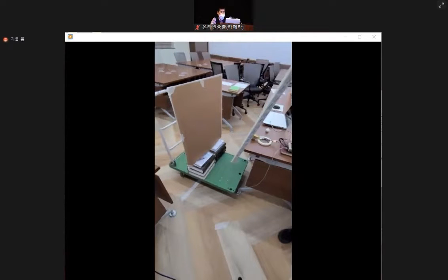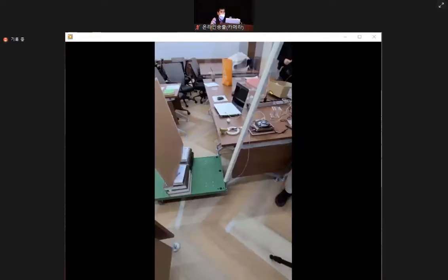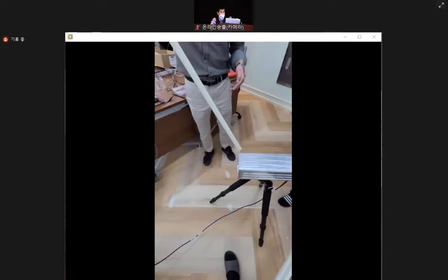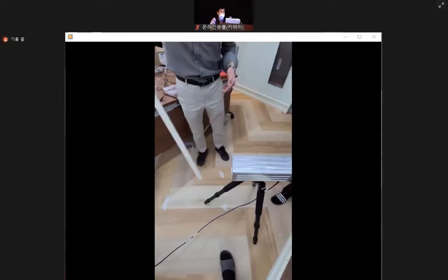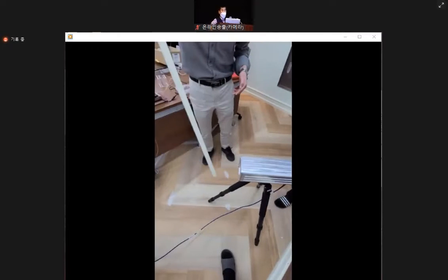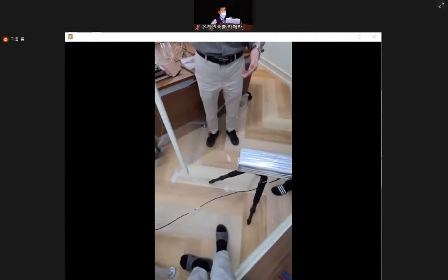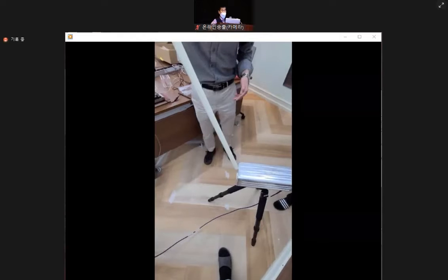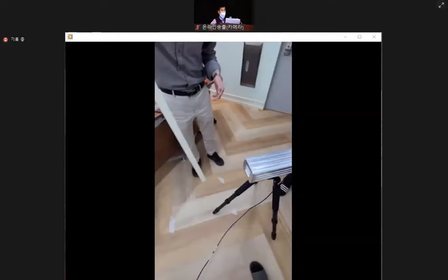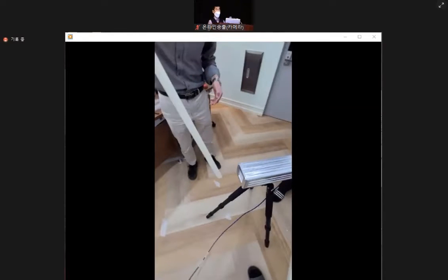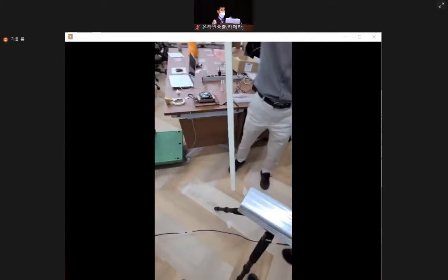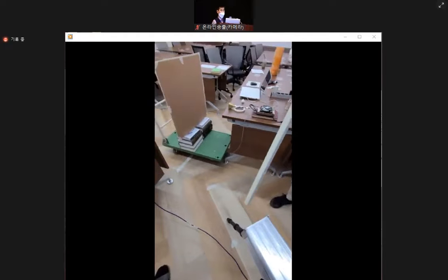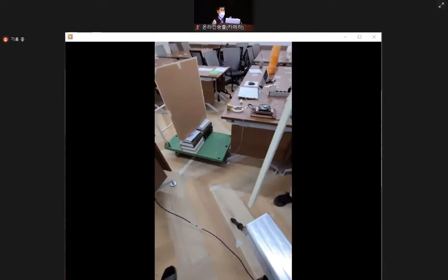But if you move the position of the probe away to the farthest point, then the noise which was around it has been eliminated and you can get the maximum strength at this position, at this angle. So we are going to check this. Let us confirm this by changing and checking the strength of the received power.